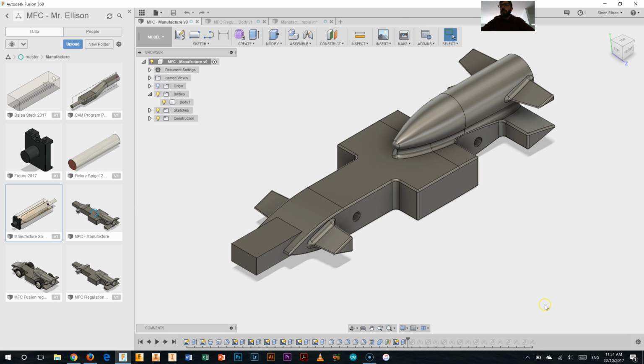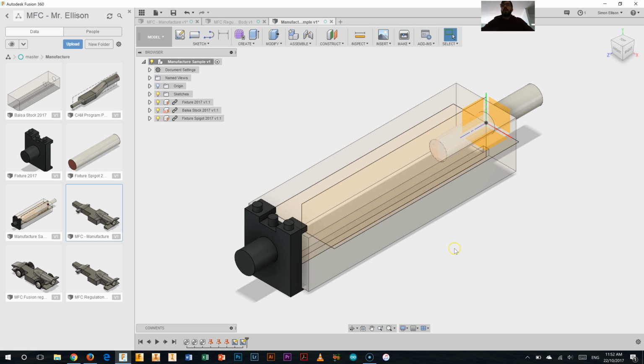Before I do that, I am going to go ahead and delete all of the wheels, etc. out of this file now that I've made a separate one, because I no longer need all that. So we'll just open that one up now that I've saved it. Oh no, we're already in it. Don't need to open it. So all these parts here, I'm going to go ahead and delete all of them. So I've just selected the first one. I'm going to hold Shift and select the last one, right click and delete. So I've deleted all the wheels and the grommets from this file. Now remembering this is a separate file, not your finished car with the wheels and grommets. So there we go. I have my car ready to go into the manufacturing model there, this one here, manufacture sample, so that I can start getting the CAM settings correct for it.